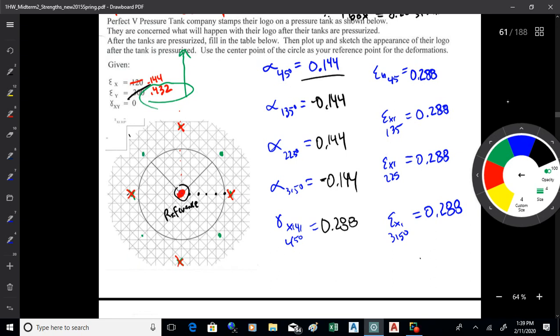So there we go. Like that. And see, that's already looking not too bad, isn't it? I mean, see how that's kind of fitting in the curve in there? If you run AutoCAD, there's a nice little command called spline that kind of creates a curve that fits points. You can fit that in there pretty well, huh? All right, but there's more to it. And actually, I think it's going to make for a little bit better situation. Maybe not, I don't know, we'll see.